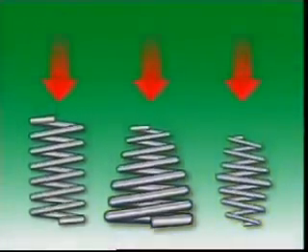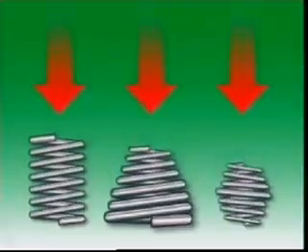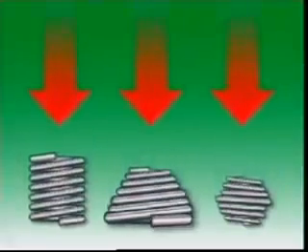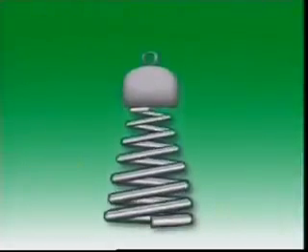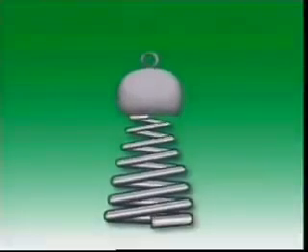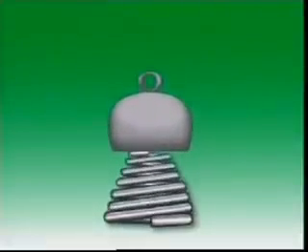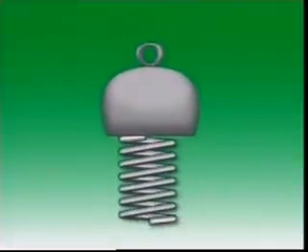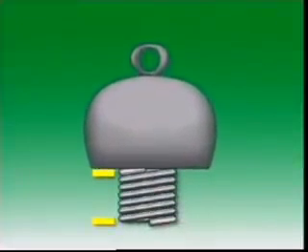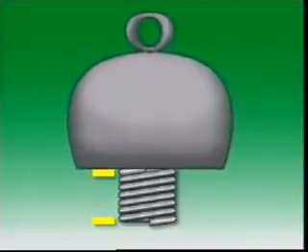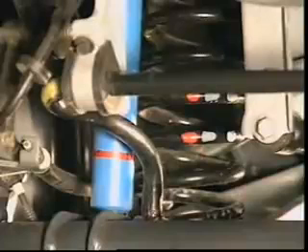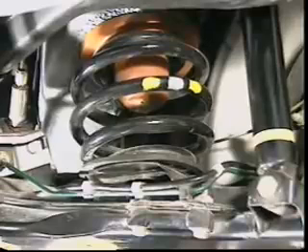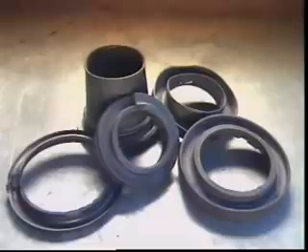As conical and barrel-shaped springs compress, they collapse into themselves. This gives a longer suspension travel for the length of the spring than for a cylindrical spring, which gives a softer ride for light load situations and a harder ride for heavy load situations. As a cylindrical coil compresses, it can become coil-bound, which limits its travel. Coil springs can look alike but give very different load ratings, which are often color-coded for identification. They normally use rubber pads to prevent transmission of noise and vibration.